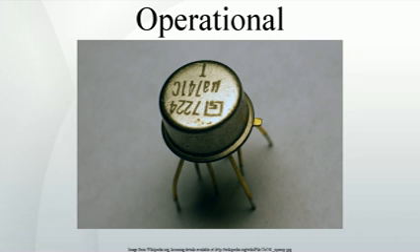Output stage voltage swing and current limiting. Variations in the quiescent current with temperature, or between parts with the same type number, are common, so crossover distortion and quiescent current may be subject to significant variation. The output range of the amplifier is about 1 volt less than the supply voltage, owing in part to VBE of the output transistors Q14 and Q20.